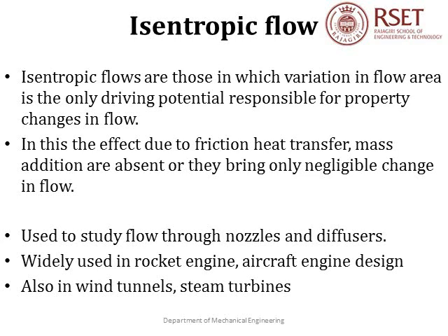Isentropic flow is a simple compressible flow in which the driving potential is the variation in flow area. As the fluid passes through the duct, the change in fluid properties is because of the change in the area. In this, the effects due to friction, heat transfer, mass addition, etc. are absent or are negligible compared to the effect induced by the varying area.